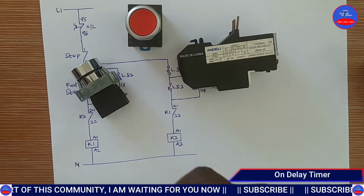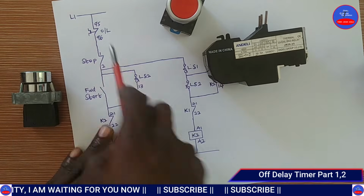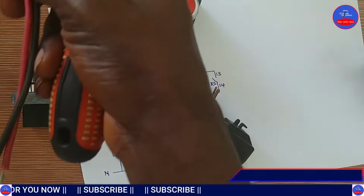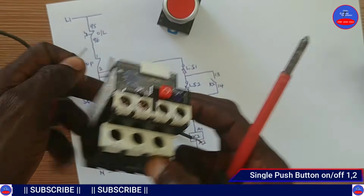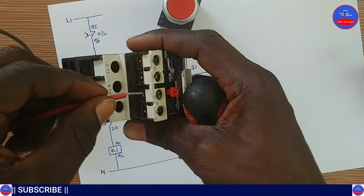Now from line 1, it came to the overload, one side of the overload, that's the 95. So this is our line 1. You wired it at 95 of this overload.